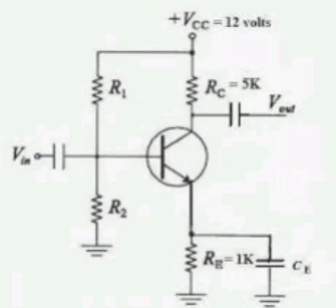Next, fourth row C. To produce a p-type semiconductor, boron is doped in pure silicon. Doping is done through the B2O3 vapor phase at a surface concentration equivalent to 3.3 into 10 power 26 boron atoms per meter cube. Calculate the time required to get a boron content of 10 power 23 atoms per meter cube at a depth of 2 micrometers. The doping temperature is 1000 degrees centigrade and DB in silicon at this temperature is 4 into 10 power minus 17 meters square per second.